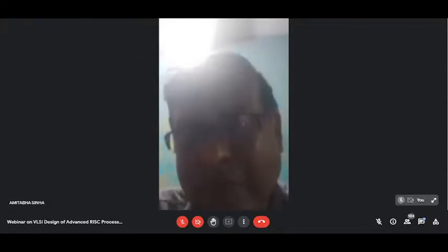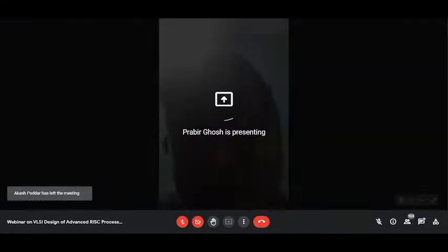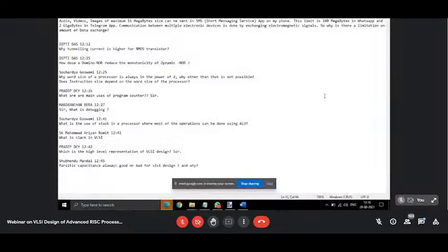When you take PMOS circuitry, in PMOS at the gate you have to give 0. Then in the drain if you give 1, VCC or VDD, then the VDD minus VTH is what you will be getting. So is it exactly VDD you are getting, not minus something? So that's why it is not.